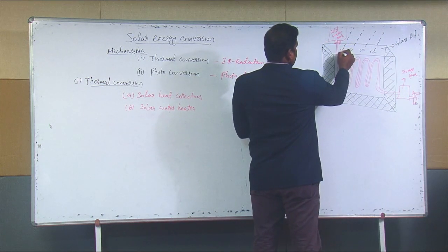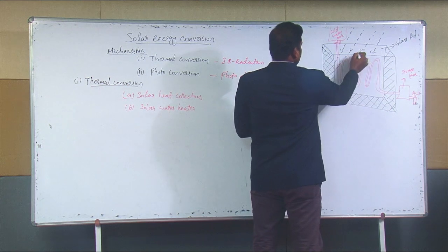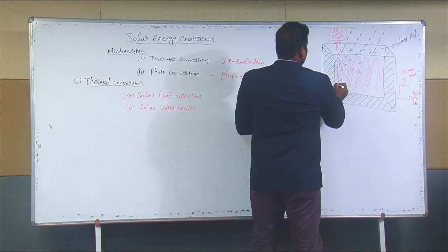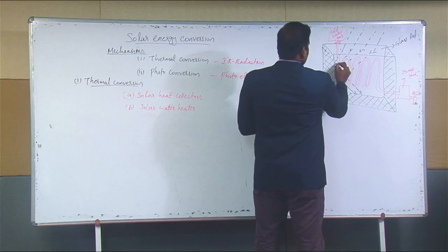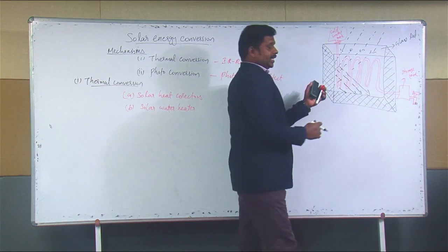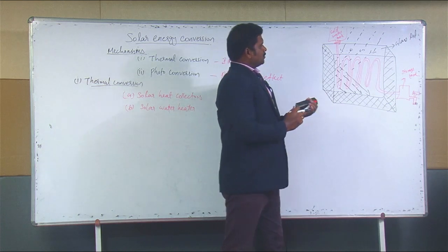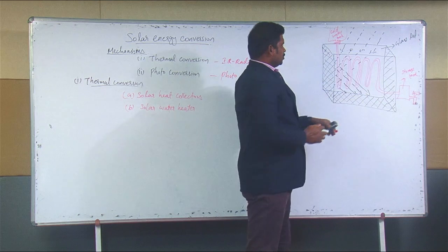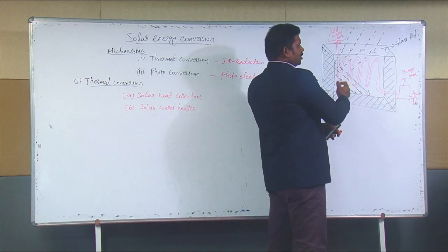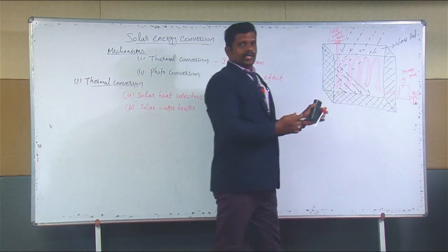The glass lid allows the solar radiation into the inside of the box. All sides of the insulated box are painted with black paint. So once the radiation enters the box from the top glass lid, it cannot escape easily. It is reflected again and again inside the box, so the box gets heated up quickly.